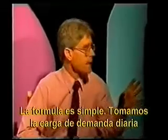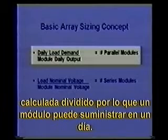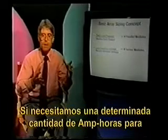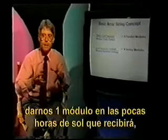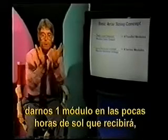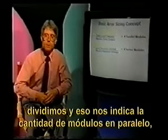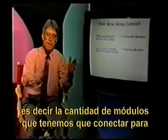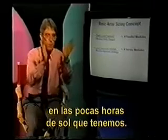What we're basically looking at is the daily load demand that we've calculated we need to supply every day, divided by what one module can deliver in a day. It's simple. If we need a certain amount of amp hours to operate our loads in a 24-hour period, we look at what one module can give us under the few hours of sunlight that it'll receive. We divide, and that tells us the number of modules in parallel, the number of modules we need to connect to give a current flow so that the battery is fully charged up in the few hours of sunlight that we have.